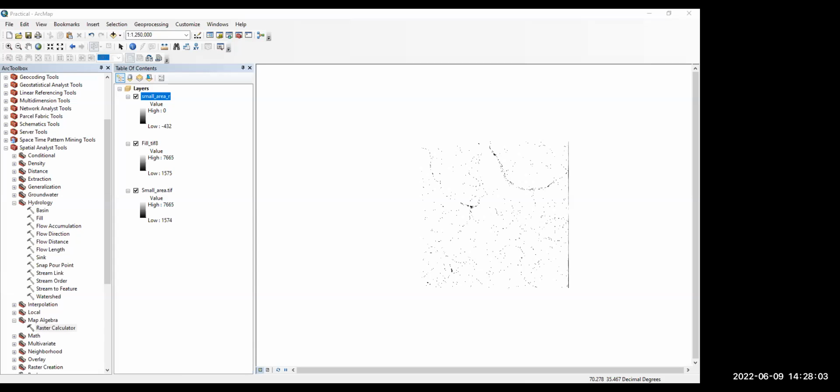So we can see the flow direction. This is basically either 1, 2, 4, 8, and 16, and so on. So the flow direction is equal to the flow direction of the elevation raster, and how the elevation raster has a downward flow toward one side or two sides is important to be shown.